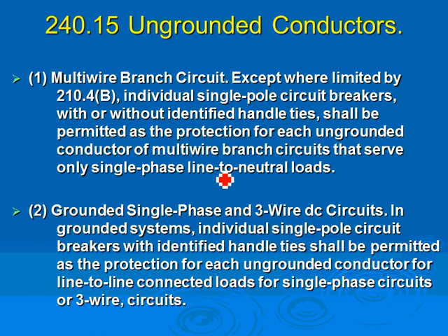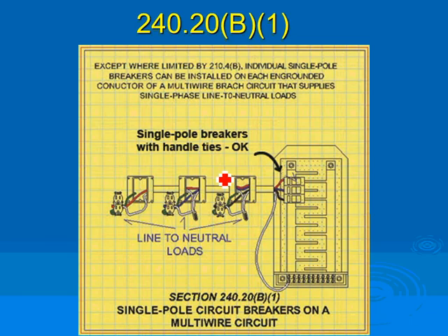So, air handling unit. You have a 40 amp air handling unit. Can I use single pole breakers 1, 2, 3 tied together with an approved handle and feed 480 to the air handling unit? Not approved. Does it work? Yes, but not approved. Because if one of them opens, guys, you're dealing with an open phase on an air handling unit. So that's what this is telling you.